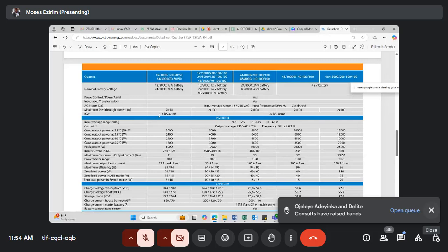Of course, you are right, but it depends on the inverter that you are using. It's good for you to size your PV in such a way that it will be charging the battery and supplying the load. That's the ideal way, but it depends on the inverter. If you are doing a DC coupled system, and you are using a battery inverter where you have an external charge controller, it doesn't work that way, because it's not powering your load directly, it's only charging your battery.